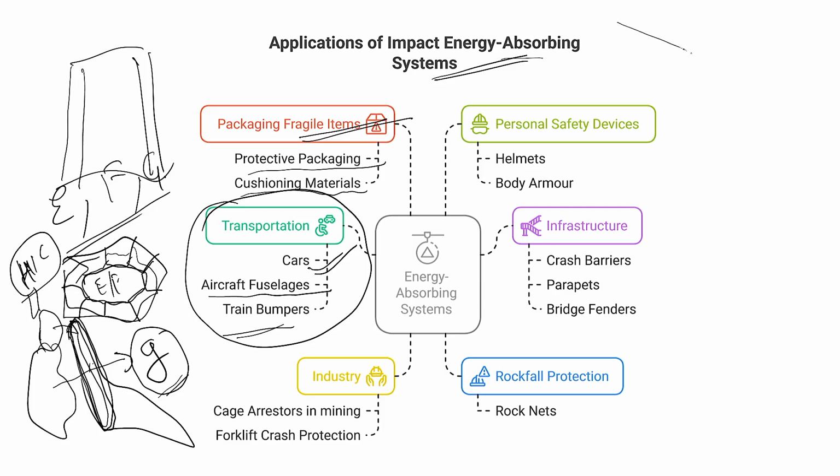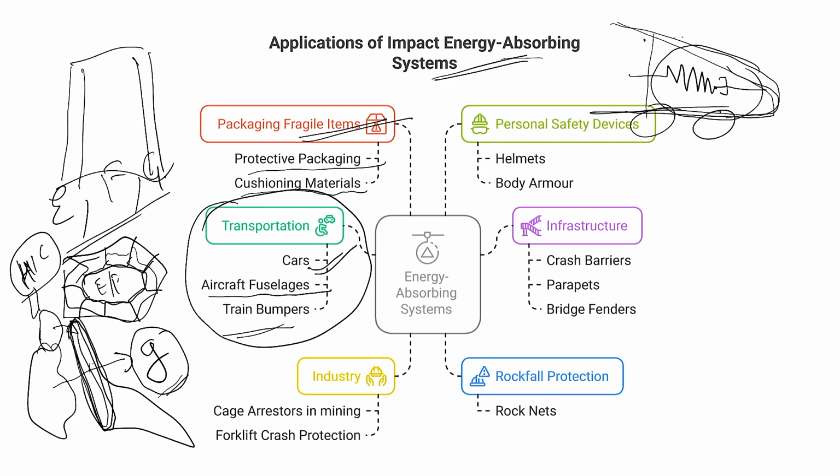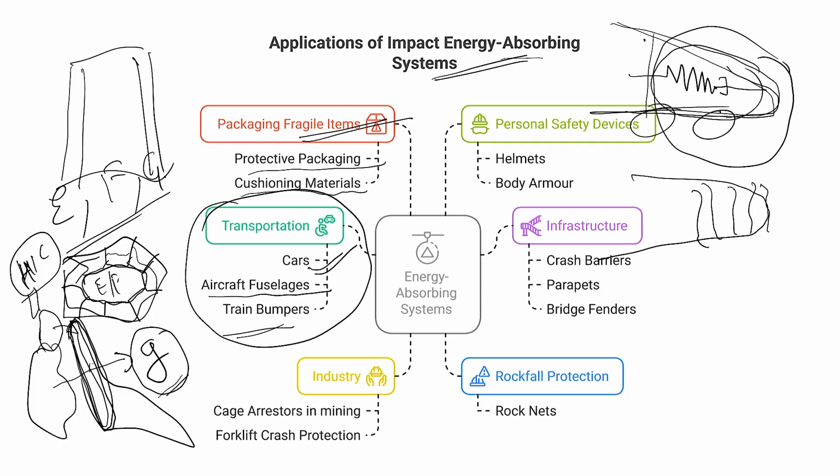In the case of high speed rails, the nose will be this type of protruding part, and if we cut open this section, there will be a spring mass system out here, or an equivalent spring mass system, where the total energy is absorbed by this system. This is also called the sacrificial layer, where the failure occurs something like this. It will be crumpled like this, but it will absorb the total energy. So, these are the train bumpers.